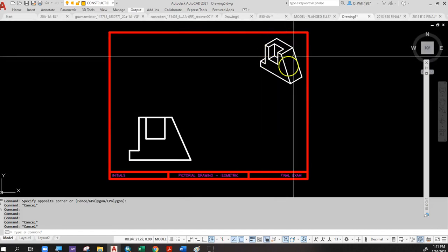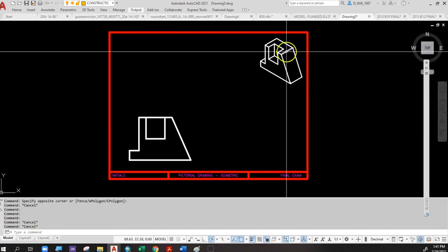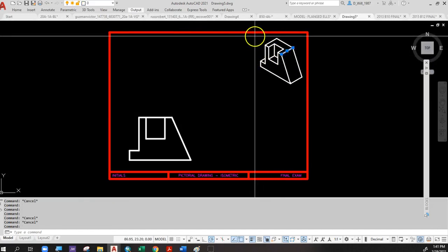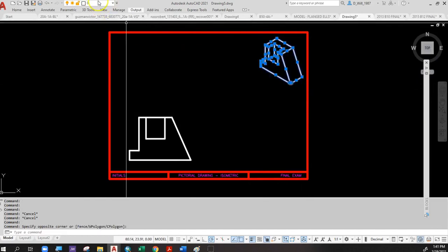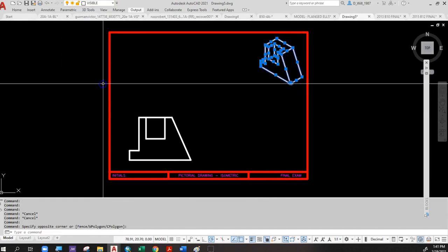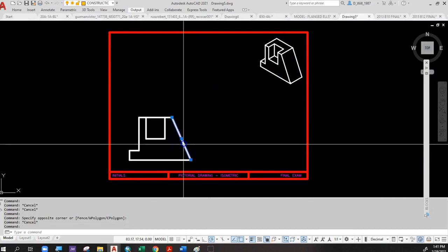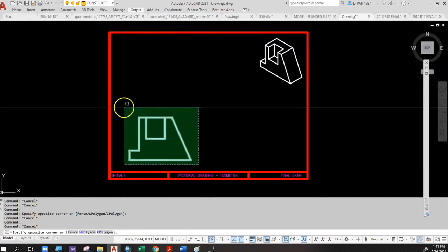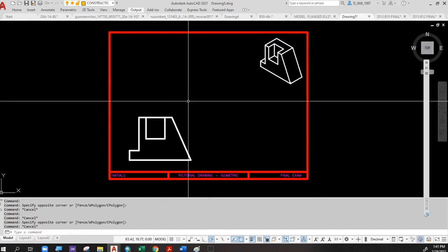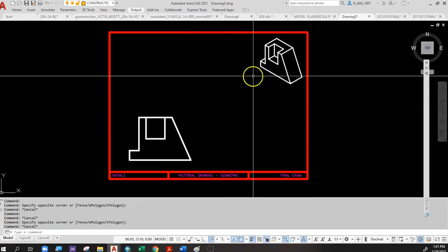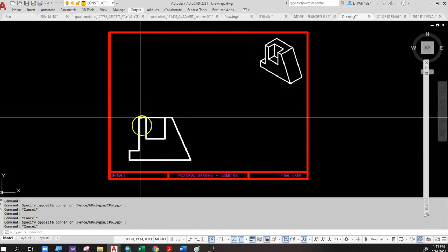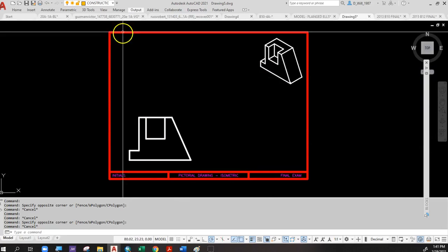And what I have here is a little isometric drawing, and this should be on the visible layer because these are visible lines, and I'm going to stick it on there. Just like these lines here are visible lines, they are on the visible layer. And visible is just another way to say the edges of the object, the edges of the profile. It's the stuff that if you picked up this thing and looked at it dead on, you would see these edges, right? That's what visible means.